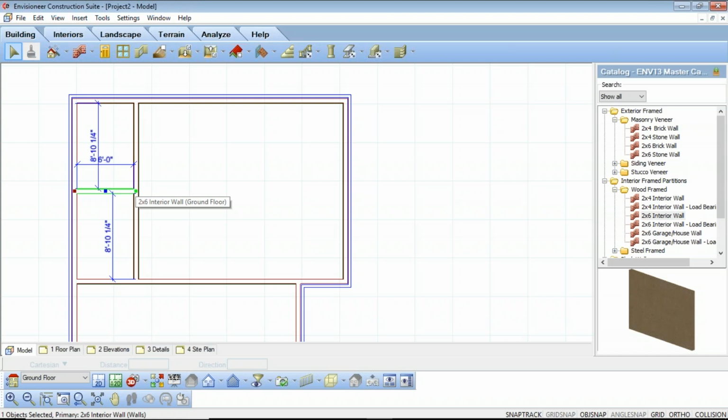Some points to remember. Before drawing walls, make sure you define your building locations and set up your units of measure and precision. A number of different drawing aids are available to help you draw, insert, and edit elements easily and accurately. You can use the Walls by Baseline tool to create an exterior wall layout with precise dimensions. Use the Walls tool for free-form design and for drawing interior walls. Use the Insertion Offset and Duplicate tools to accurately add walls to your model.